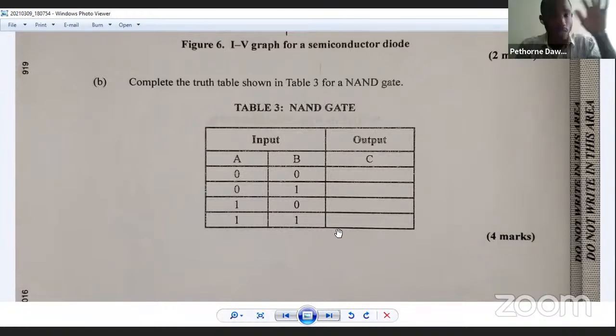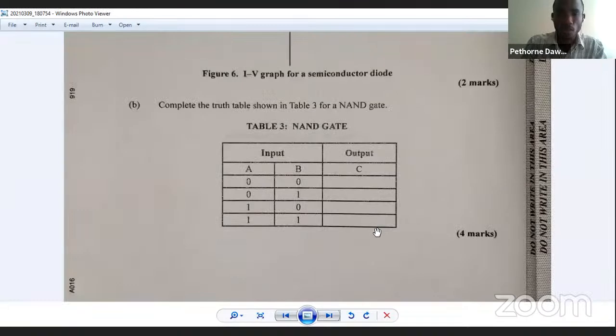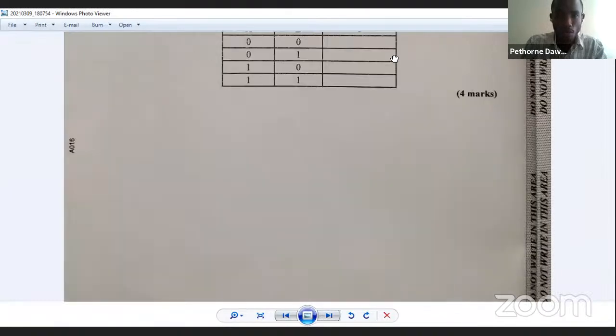But for now, for CSEC, I know definitely for CSEC, NOT, AND, OR, NAND and NOR. Those 5 gates are what you should know. And as I said, the NOT gate is an inverter. It's either 0 input, 1 output, or 1 input, 0 output. So it just flips it. And then you put the flipping or inverting characteristics with the other gates to give you the NAND and the NOR. All right. So that is a little info there if you weren't aware.